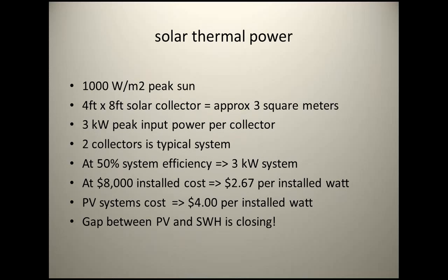The heating element on your conventional electric water heater is a 4.2 kilowatt electric element, so that gives you an idea. This input power is 1.5 times what that 4.2 kilowatt electric heater will do. It's a 240 volt, 4.2 kilowatt electric element inside an electric water heater. Okay, system efficiency is only 50%. Then we're down to 3 kilowatts, and that's not too bad for total system efficiency.